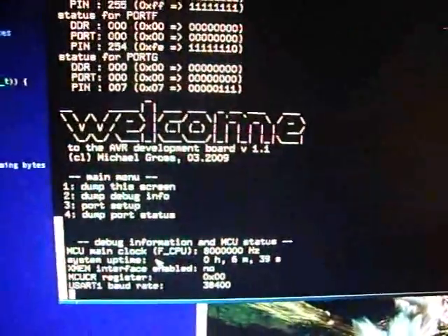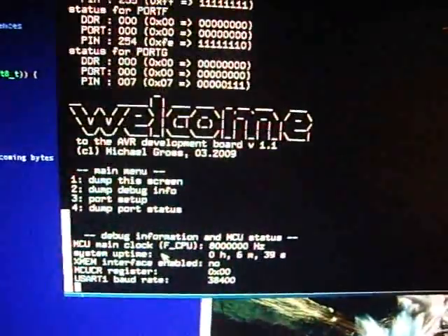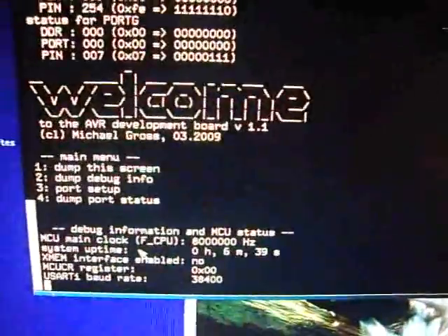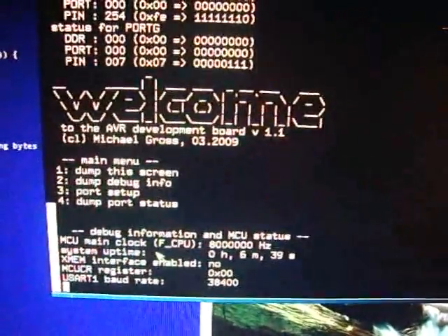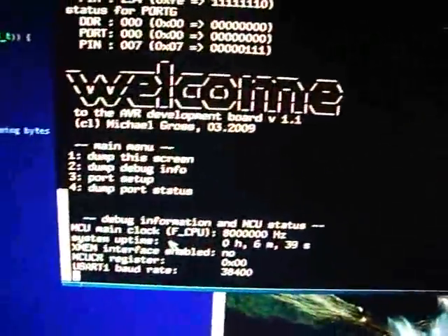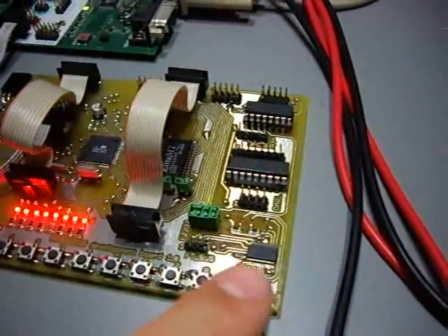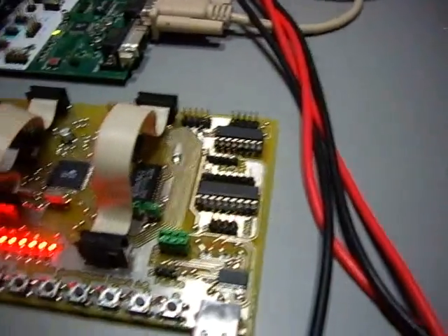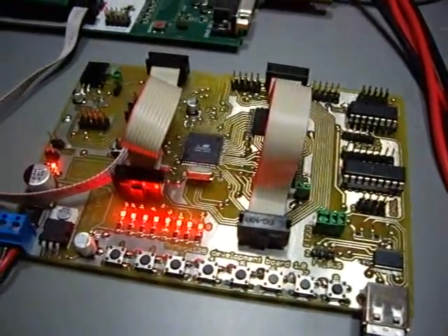So with this, it is possible to write sort of an application, a little console program which allows you to interact with an application, right, and give some controls or output stuff like here. And this is all done via the serial line interface, the USART interface, which is then converted into a valid USB connection by this USART USB bridge. And this is just the demonstration for this capability for this chip.